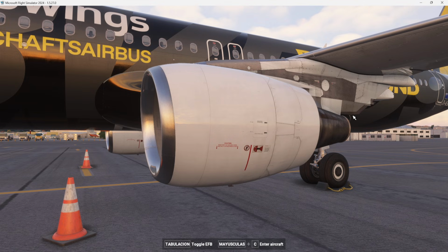Basically the fan rotates, and the air passes. So this 80% goes by the bypass, which is like a small tube from here and from here. And then we have 20%. This 20% is going to pass by all the stages that I'm going to talk about step by step.